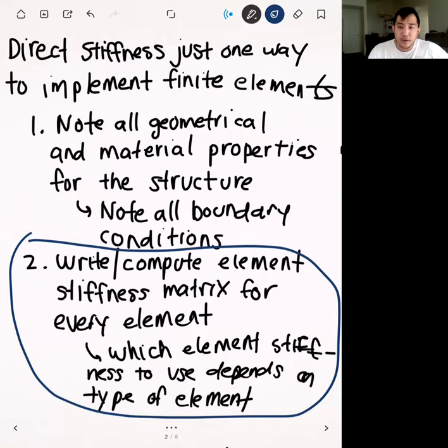And that's kind of how the direct stiffness method gets its name, because the direct stiffness method basically works directly off of the governing equations for that type of element. Okay? And so for a spring, we saw that the element stiffness matrix simply got by getting the force and displacement relationship between them, and then basically just making one equation the negative of the other one.